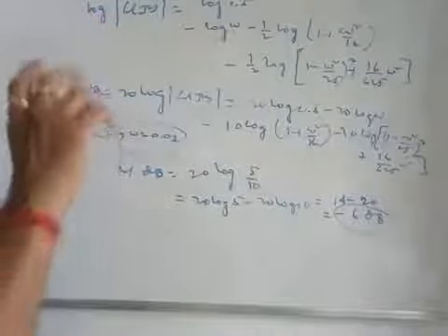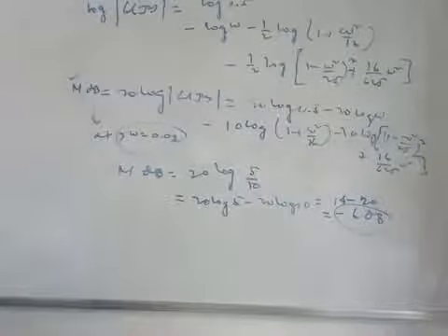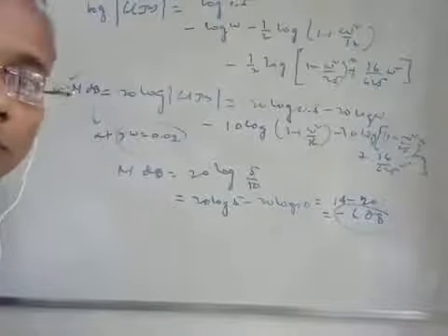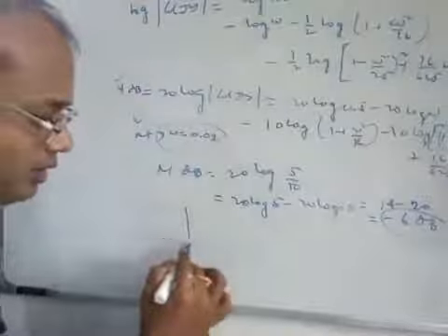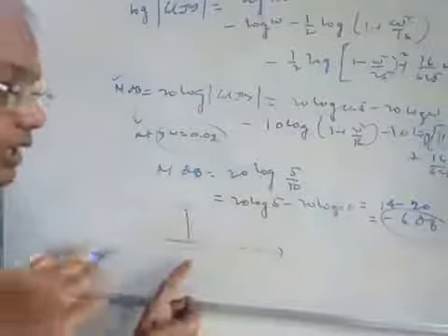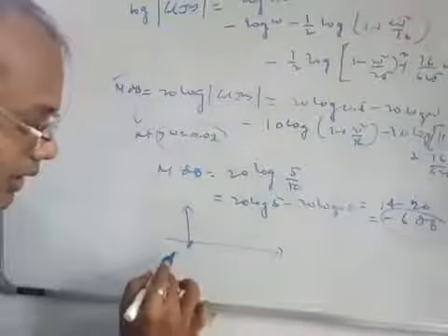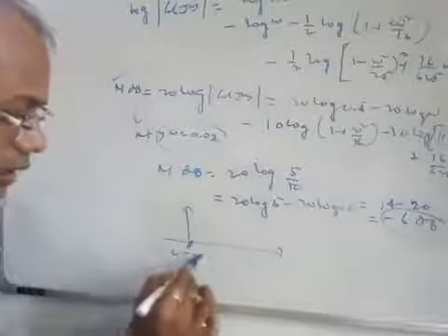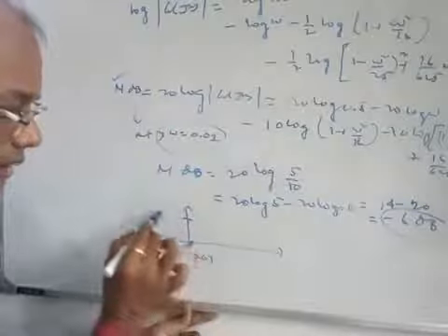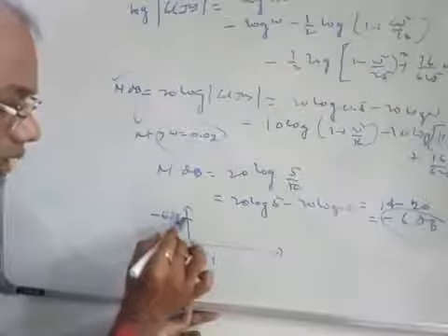Now, up to this, whatever calculations we have made, what is the conclusion we can see? We just draw this rough graph like this. The graph will be like this initially. That means when you put this value in the semilog graph paper, the initial value of omega was 0.01, and the magnitude at this point was minus 6 dB. So you get this initial magnitude.